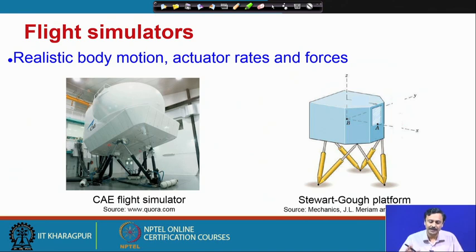So, that will give the pilot a feel of the aircraft motion, because in a rotating frame like that it's not very intuitive to understand how different forces act, because it becomes a non-inertial frame, as you know. And the forces that these actuators must provide in order to keep this in equilibrium, in quasi-static equilibrium.